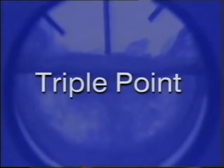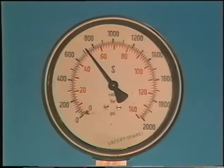In the first sequence, the CO2 will be cooled by forced evaporation to the stage where it passes through the triple point. The cell is filled with liquid CO2 at an ambient temperature of 15 degrees centigrade when the equilibrium pressure is 49.7 bar gauge.